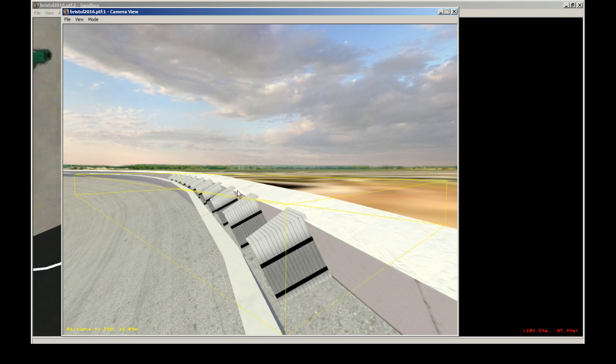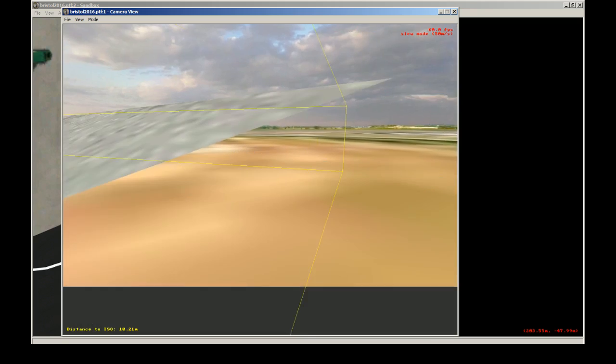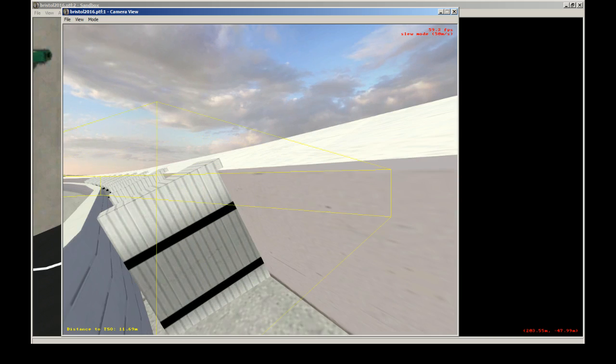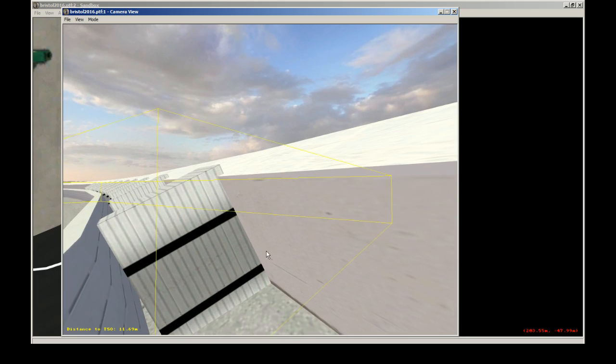You're going to have to do some adjustments with your wall heights in the corner because it's just not drawing it correctly, and I don't know if I can visually show you exactly what's going on. The height between here and here is not exactly what you set it to. The outside of that wall is either going to be way too tall or way too short.